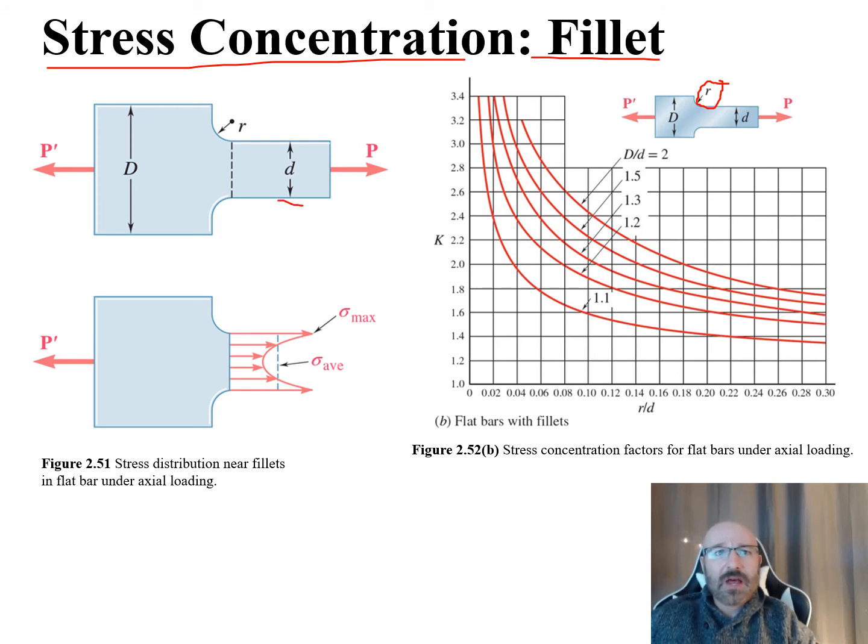What we really want now is to think about the stress concentration factor, because when we're doing a dog bone specimen, we don't want this to be our highest stress concentration up here. We don't want this to be the area that fails. We want to minimize that and make the area that fails down here at the minimal cross-sectional area of the dog bone specimen. So we have this ratio here.